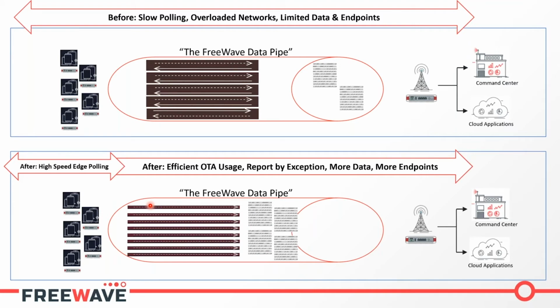And also due to our protocol conversion, our edge storage, and our edge data processing, we're also turning that into useful real-world data for your industrial operation and your business, represented here on the graph by these temperature and pressure icons. And from here, via MQTT, this can go to your SCADA system, your enterprise dashboard, your cloud, wherever you need the data to go.